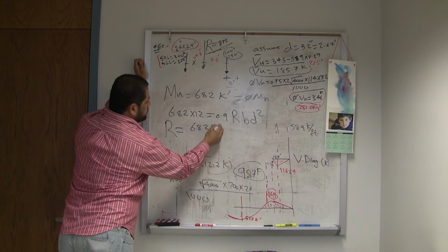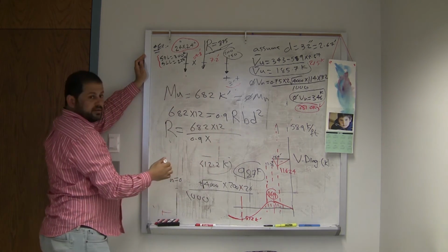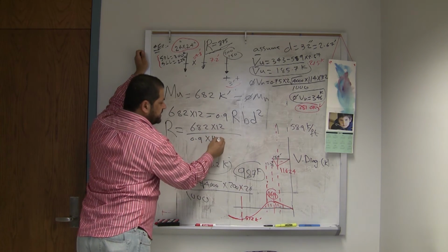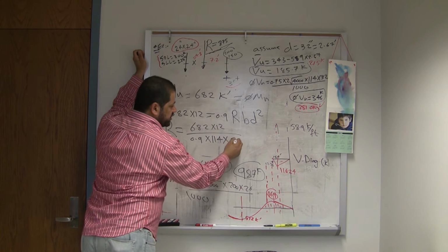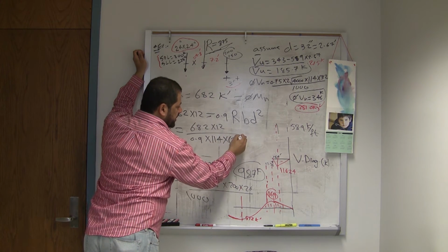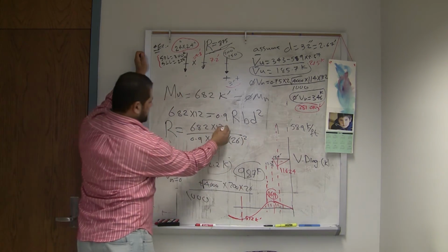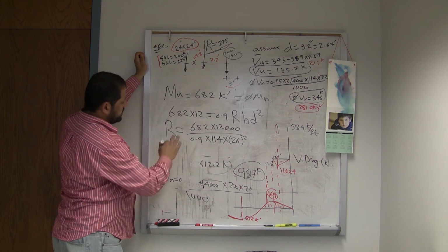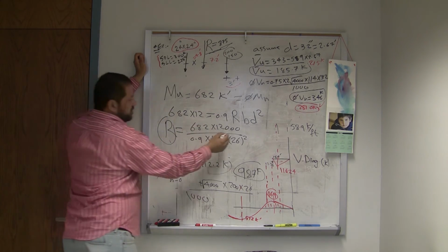Okay, so R equals 682 times 12 divided by 0.9 times what's b now? It's the full width, 9.5 foot, times 12, which is 114 inch, times d, which is 26 inches, squared. You do that. You may want to put 12,000 to change it. If not, it's not going to work. It has to be in psi. So how much?